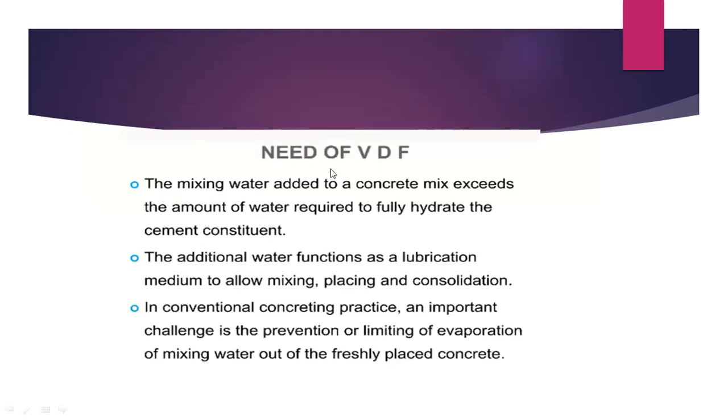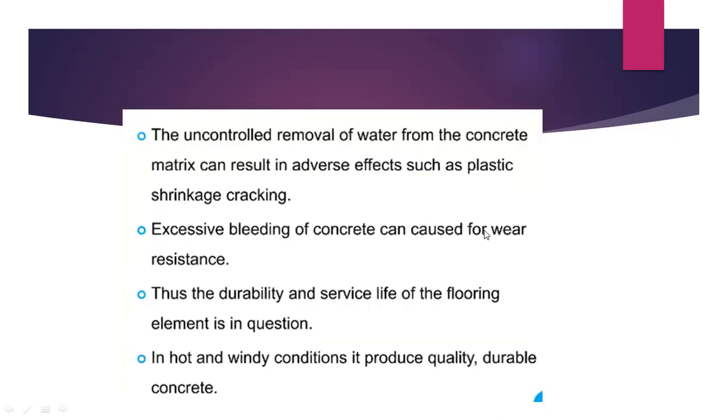And as I said in the earlier slide, we have discussed the mixing of water. It helps in the hydration process. The first point is hydration, and the second is lubrication. It acts as a lubricant so that the concrete will be able to mix well, place well, and consolidate. Those are the advantages of water, but if you add excess water, it results in some disadvantages also.